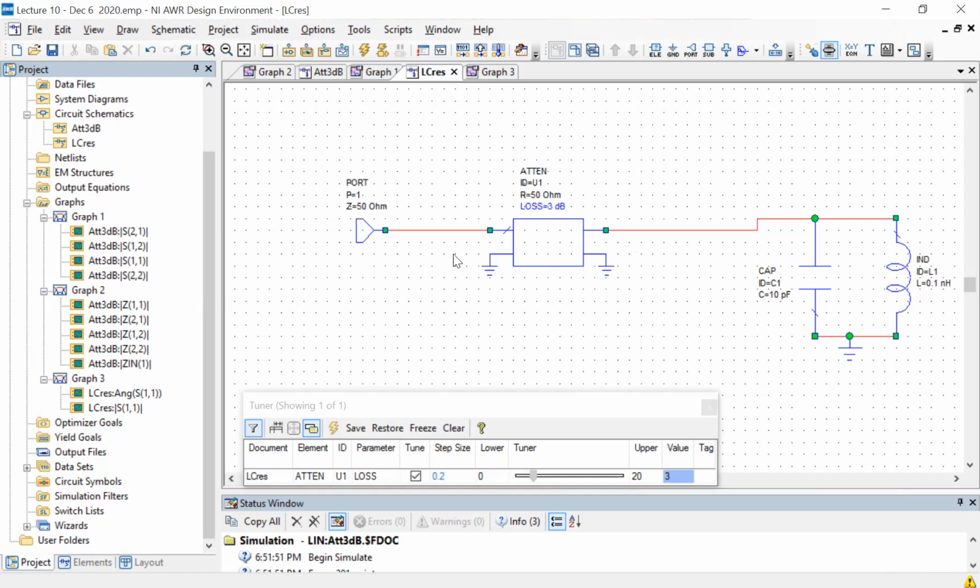And this again is a practical aspect: you will suffer signal to noise ratio issues if you have a setup like this where the reflection path contains losses. There are some configurations where this will not matter. I'll discuss that later on when we look at those kinds of setups.